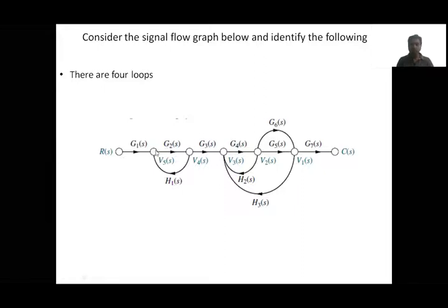Here at this point we have a feedback loop. So this is a feedback loop, and again here at this point we have an outgoing and incoming signal. This is another loop, and also at the next node we have a signal like this, and it can't go like this, so it is not the feedback path. It is a feedback path coming in this direction, and till this point this is a feedback path.